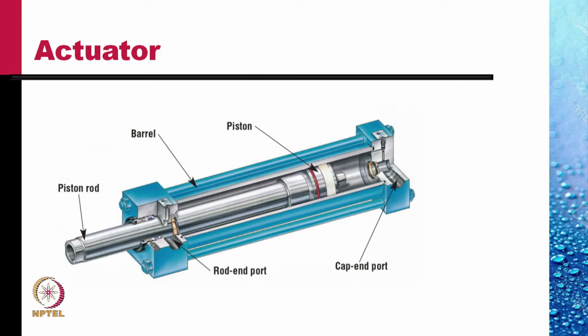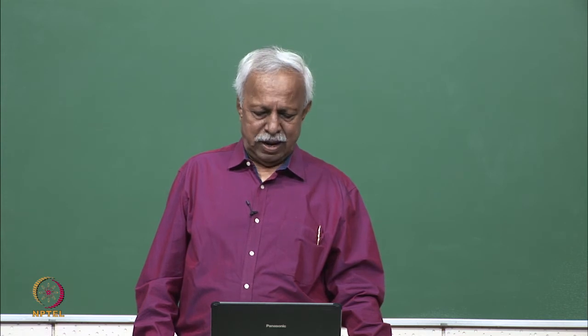This picture shows a pressure actuator used in all kinds of hydraulic machinery. What it does is that fluid at a large pressure is pumped into it, and as it pumps, this acts on this piston, and this piston moves in that direction, applying a force in whatever equipment that we want to apply force at.